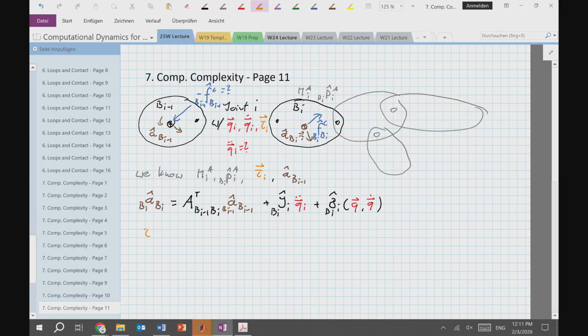We also know that there is an inherent relationship between the torques, the motor torques at that particular joint, and the overall 6-dimensional constraint forces, which uses the same Jacobian just in its transposed form and gets multiplied with this vector of constraint forces given in BI coordinates. So I'm basically just restating things.